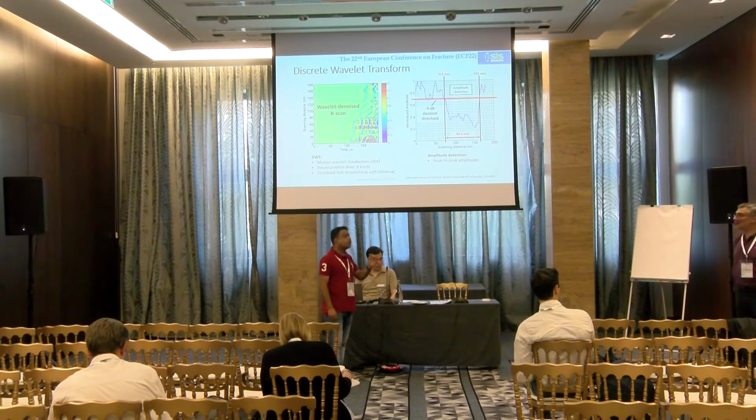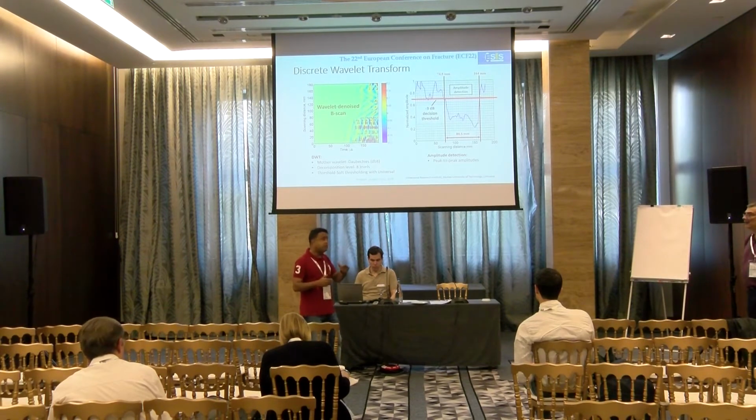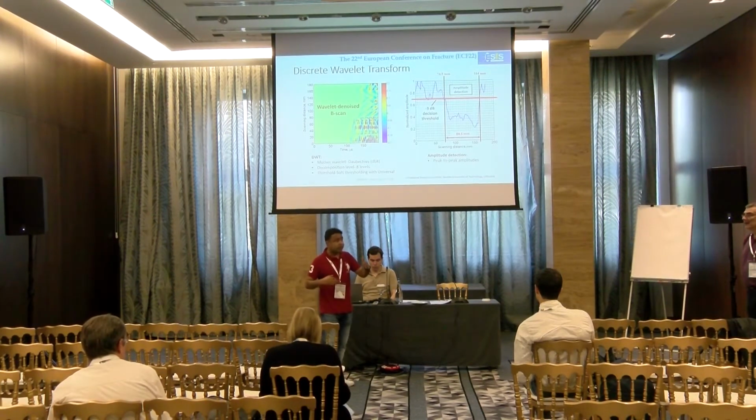Yes. Because in the composite structure the guided waves are dispersive waves. They have, for example, the S0 mode, in plane in the direction of propagation, and perpendicular to the direction of propagation, and they have out-of-plane modes. The 3 modes are S0, symmetrical in the direction of propagation, the A0 mode, an out-of-plane asymmetric wave mode, and also the shear horizontal mode. So we have 3 modes.